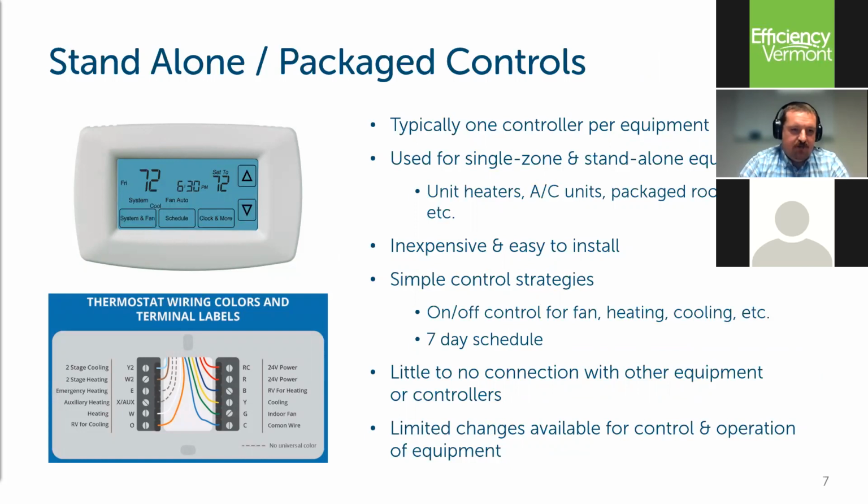It was very common to use the traditional thermostat wiring. So you had fan call, heat call, stage 1 and 2, cooling call, same thing. And a lot of the control tended to be very simplistic, kind of on-off control. I could turn things on and off, but I couldn't really adjust things. I couldn't modulate things unless I had additional components. A lot of these programmable thermostats also had a 7-day schedule. So you would have to change for daylight savings time, leap years, that kind of stuff.